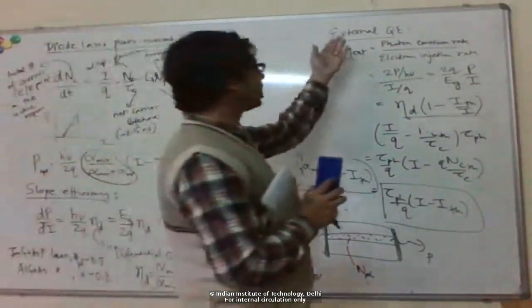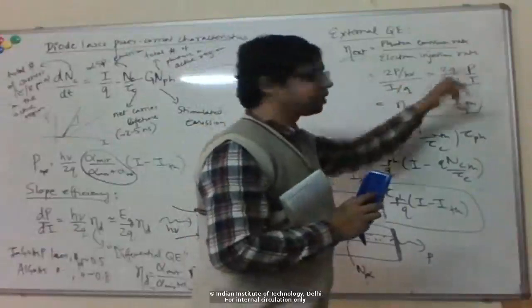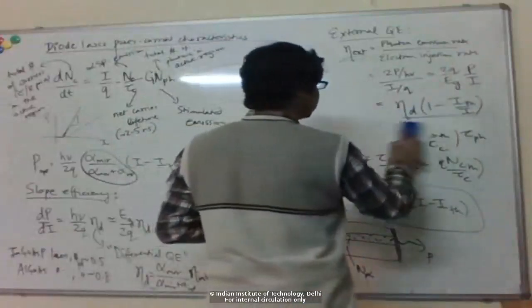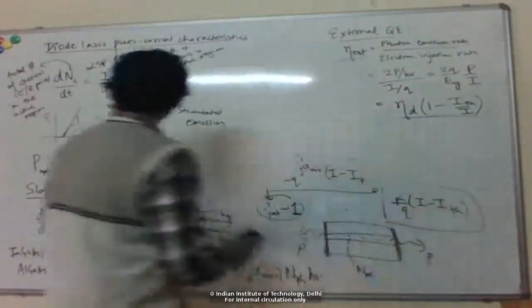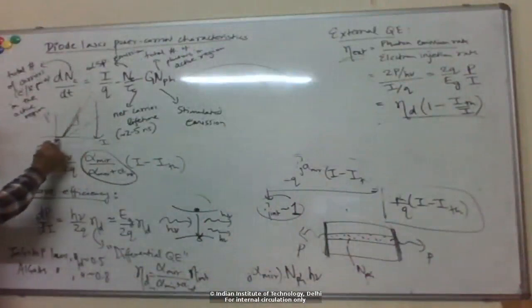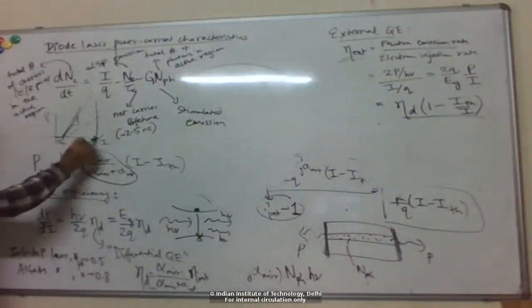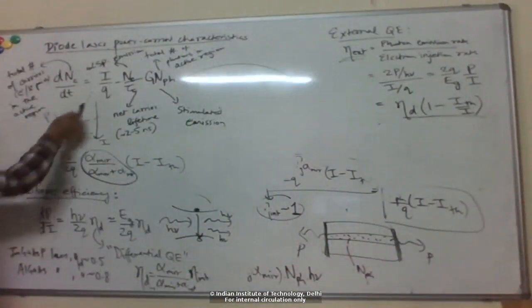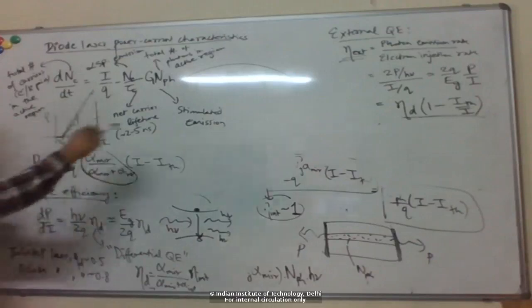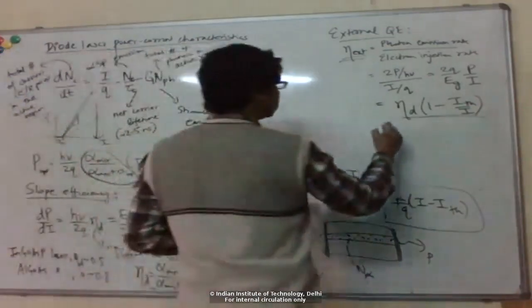This gives you the total efficiency, power divided by current, so it's always smaller than the slope efficiency. But if you go much above threshold, so the I threshold is very small compared to your operating current, then the slope efficiency is almost just right. This intercept doesn't matter too much.